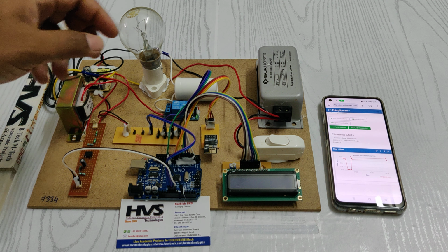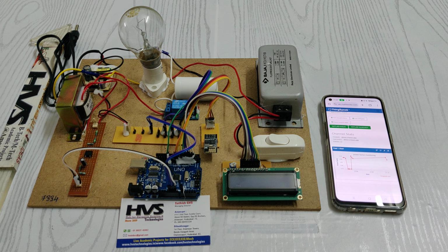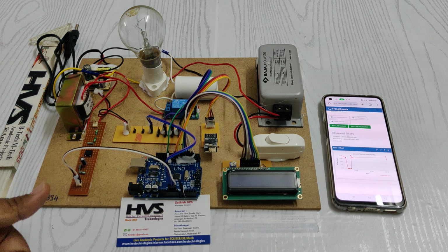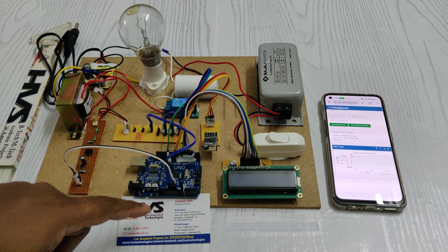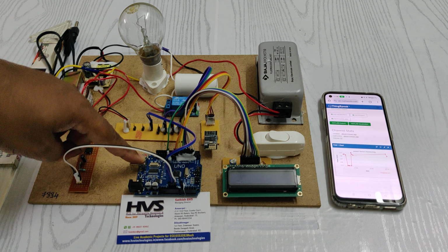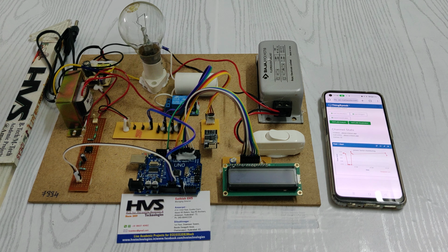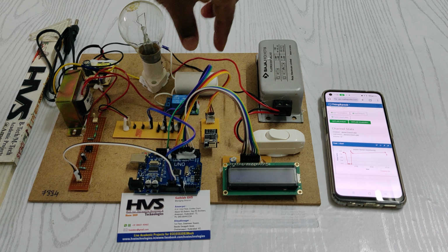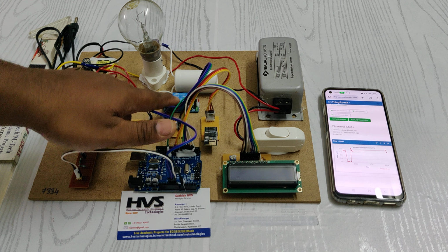As we know, an inductive load will lag the current waveform, and a capacitive load will lead the waveform. Whenever this inductive load is detected, the current waveform lags and the power factor comes down from 1 to 0.9 or 0.8. Then the Arduino UNO will continuously measure the phase difference between these two waveforms. When it lags, the system will turn on this relay to attach this capacitor in parallel to the R plus L. R and L are in series, and to these two loads we place this capacitor in parallel, and that will be connected with the help of this electromagnetic relay.